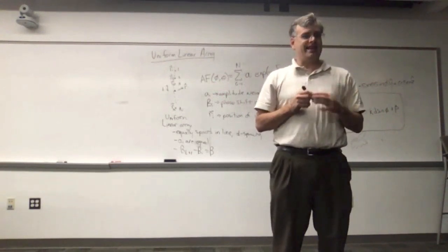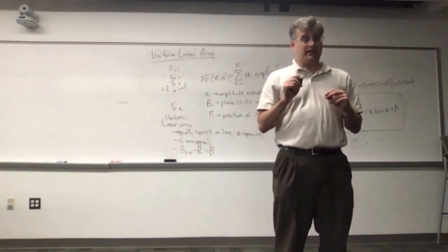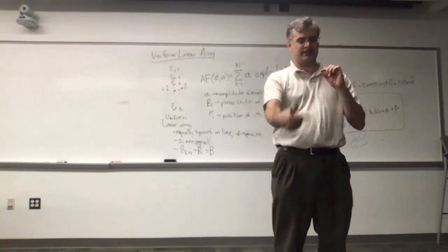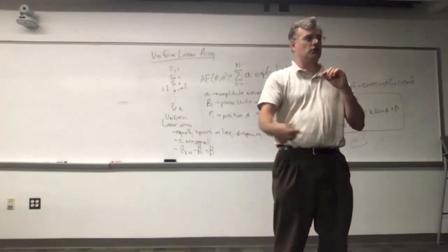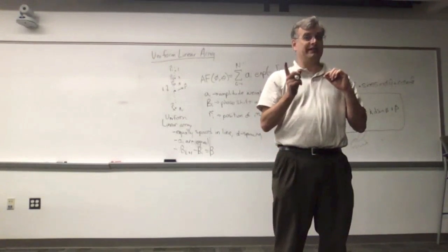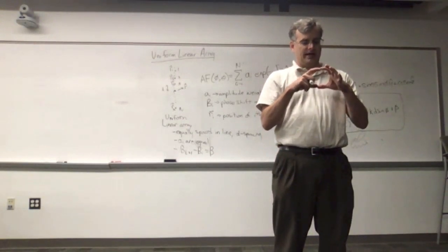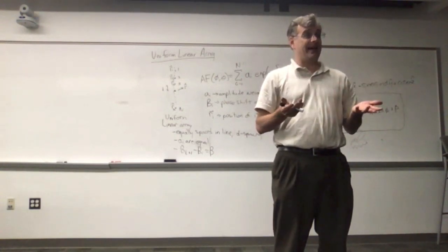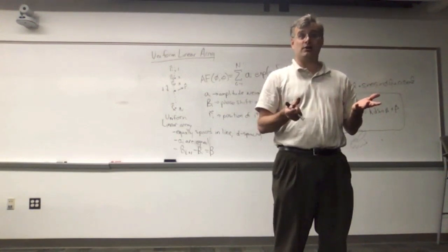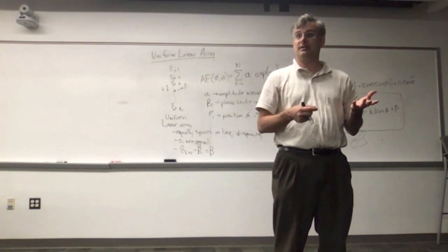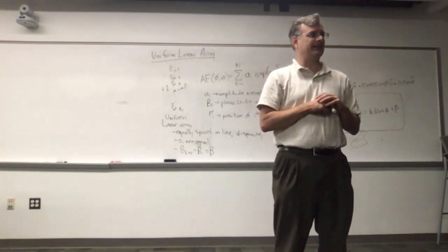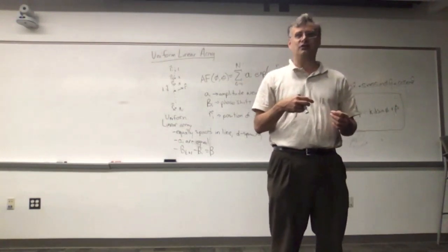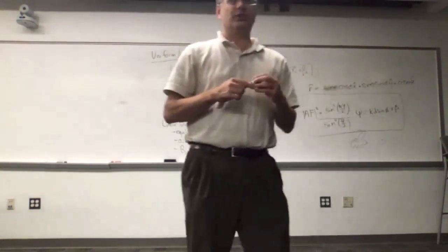That's nice. And then we'll talk about helical antennas, which winds up being really just a bunch of winding, electrically large helixes, just like a coil, one strand of a DNA. But what's really neat about that is that you can model it as an array of loop antennas, a uniform linear array, that just happens to have Hansen and Woodward end-fire phase shifting between the elements. You get this beautifully directed antenna. It also happens to be really broadband because there's this kind of weird traveling wave correction factor in it that gives it almost 2-to-1 bandwidth, which is really cool too.